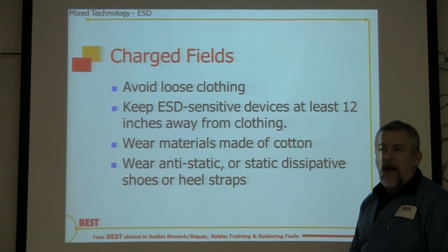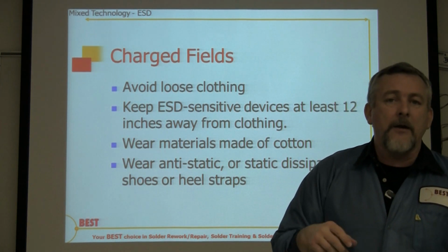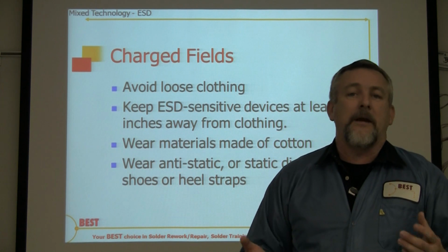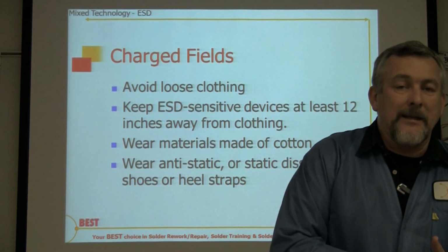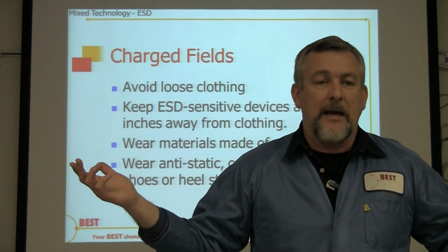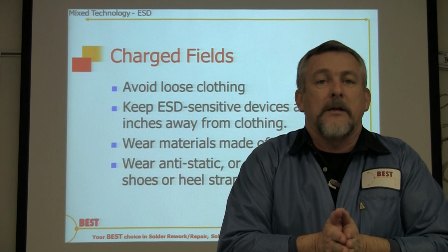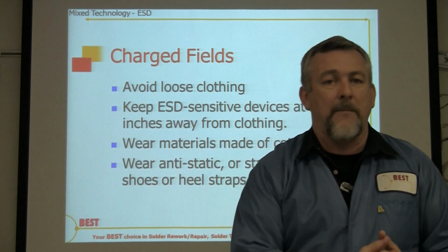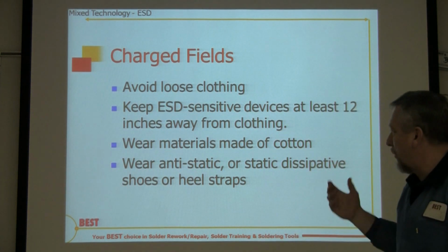Wear materials made of cotton. But remember, if you're wearing cotton, a lot of times people iron them or have them starched up. Well, that defeats the purpose of the cotton in avoiding static electricity. When I was in the Marine Corps, that was one thing. You had to be pressed up really nice every day. So we had to starch our uniforms so they looked nice and crisp. Well, guess what? We were defeating the purpose of the ESD program, because our clothing is made of cotton so it can breathe a lot easier. But that's what we have to do.